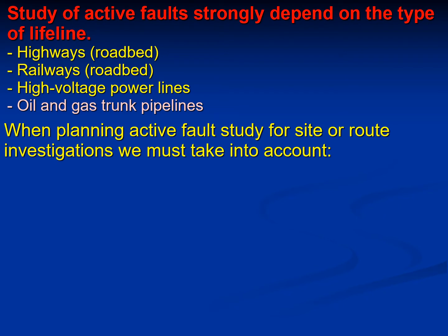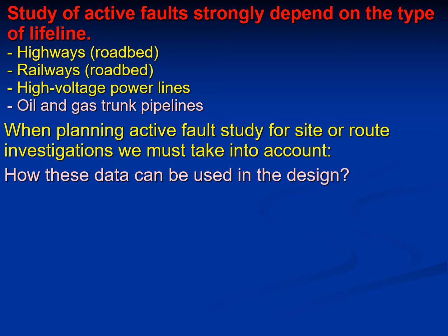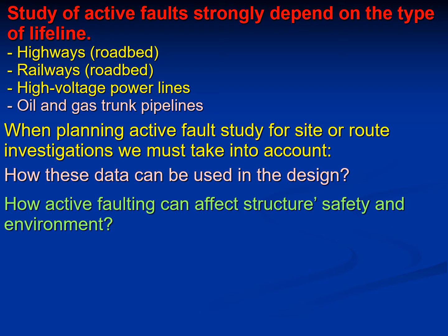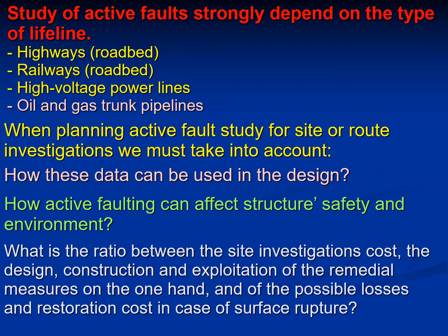When planning an active fault study for site or road investigations, we must always take into account how this data can be used in the design, how active faulting can affect structure safety and the environment, and what the ratio is between the site investigation cost, the design, construction, and exploitation of the remedial measures on the one hand, and the possible losses and restoration cost in case of surface rupture.